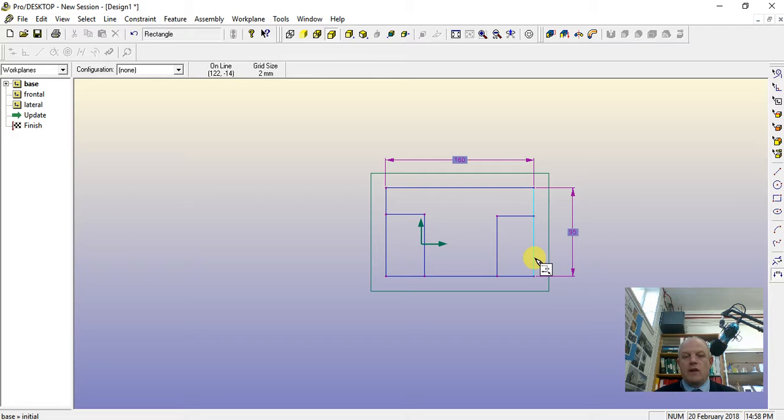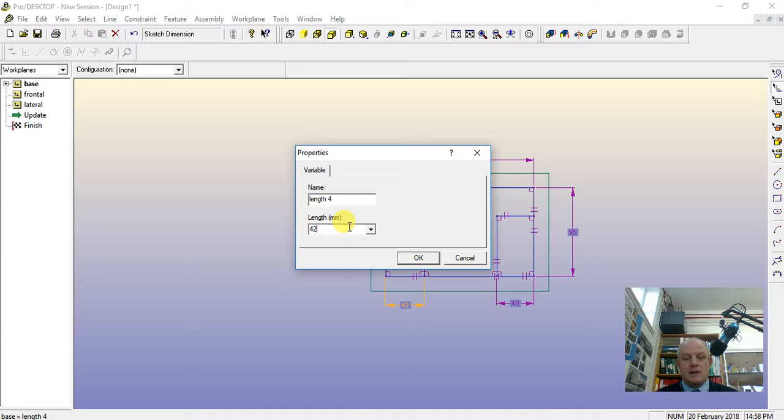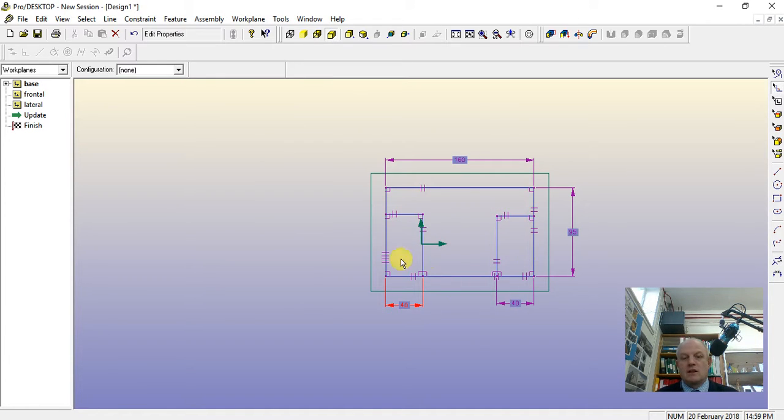You can hover on that outside line, click on it so it goes red, then hover on the inside line, keep your finger down now, and as you drag outwards, it will show you the distance between the two. I actually want 40 millimeters, so that's perfect. I'll try again. Click on the outside line, hover on the inside line so it turns turquoise, keep your finger depressed, drag down, and it's slightly out, it's 42. So here's my chance to change it. Double click, triple click, and I'll just change that to 40. Say OK. So just tucked it in nicely so they're the same.